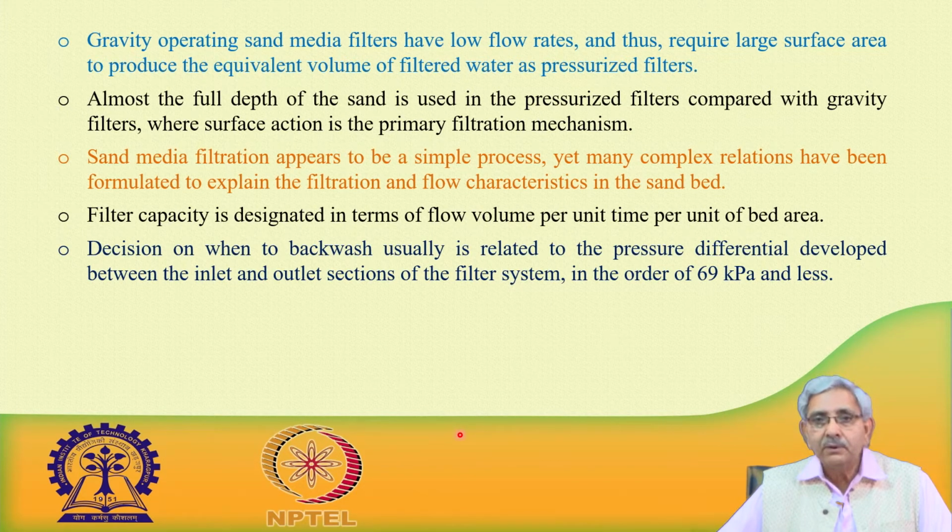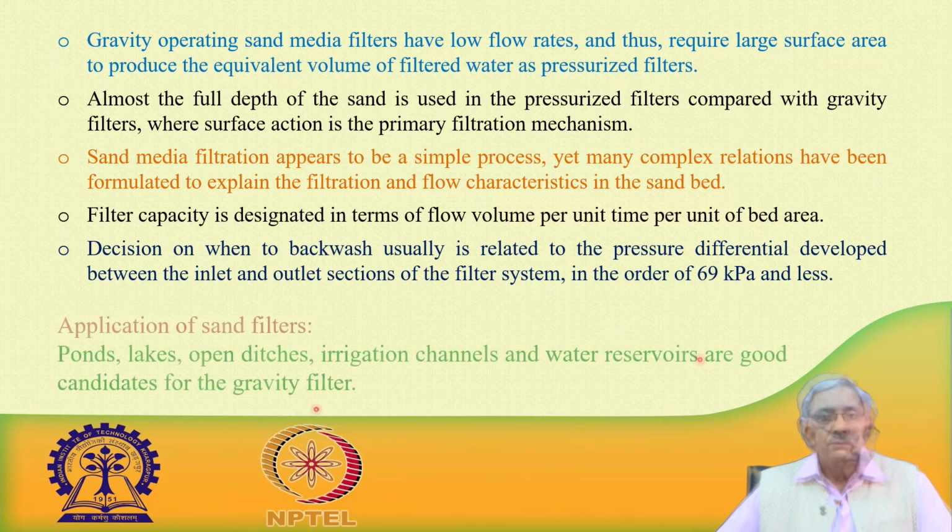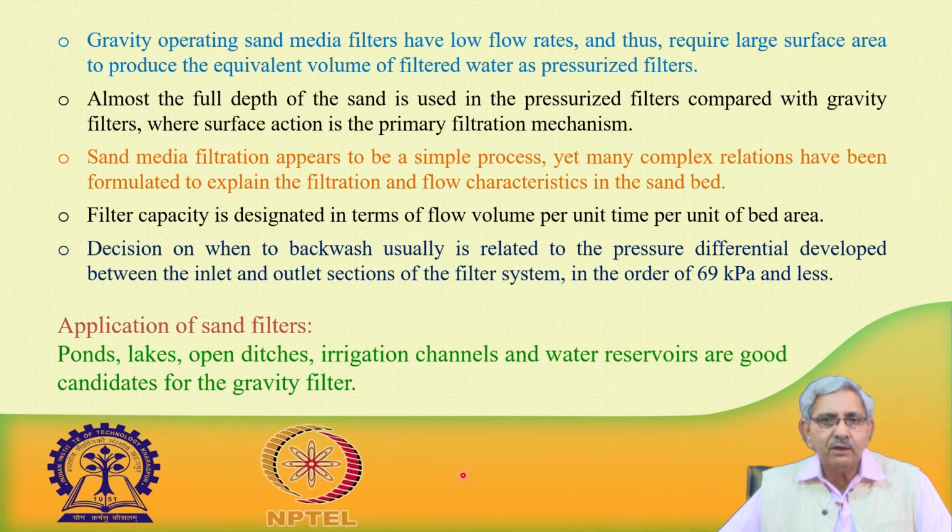When the pressure difference across the filter exceeds 69 kilopascal, the filter needs backwashing. This type of sand filter is used for water from ponds, lakes, open ditches, irrigation channels and reservoirs.